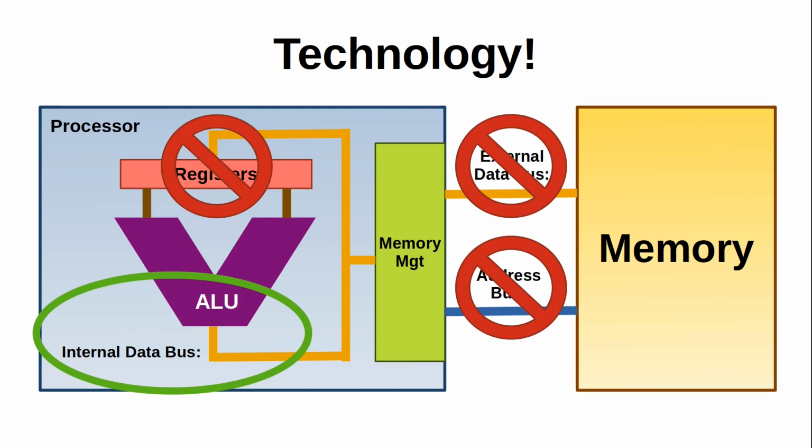That has 32-bit addressing internally, but the address bus is not actually 32 bits wide. And the external data bus is definitely 16 bits, because it's a 16-bit CPU on the inside, that original 68000. So that's what we're really going to be talking about: internal 16-bit technology.